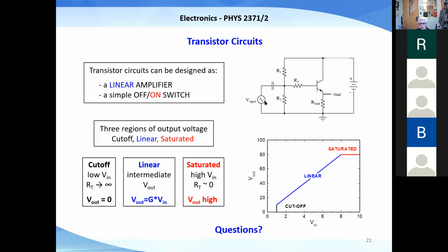Suppose the microphone here was plus or minus 1 volt. Okay, so if this resistor network, this voltage divider, gave you a voltage of 5 volts here, and then you had plus or minus 1 volt coming out of the microphone, then you'd be down here at 5 volts, and the microphone would go up 1 volt or down 1 volt.